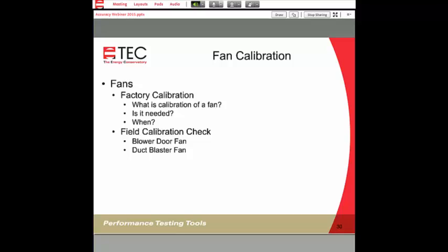How does battery voltage affect accuracy, if any? We want to say that it doesn't affect it at all. When your gauge starts to show low and then eventually cuts out, that means that we've already built in internal values to say that when there's only so much voltage, and I don't remember what the number is exactly, it might be 6.8 volts, if it reaches that value, it can affect reading.